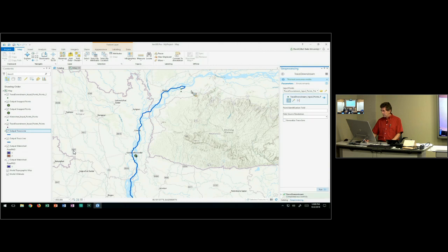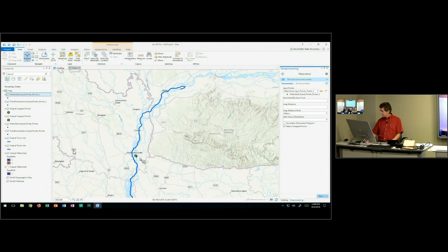Now you can see there's the main flow path as the DEM has delineated, going down the Brahmaputra River. If I was interested in an outlet over here, I may want to switch to the watershed tool again. Let's create an outlet point. Now, it's a little bit fiddly.